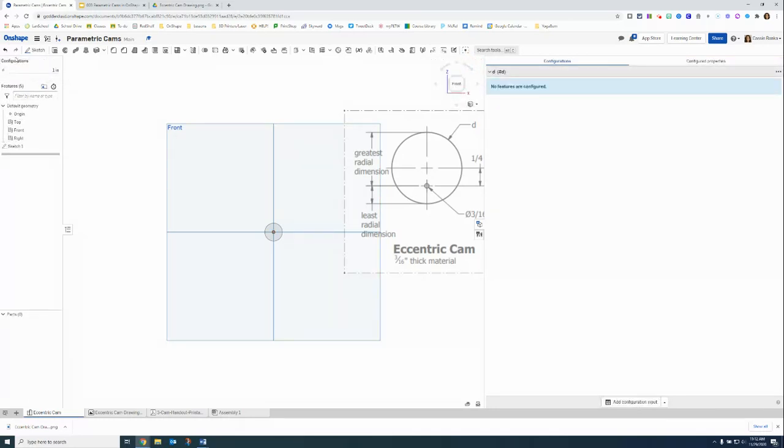Now over here on the left-hand side in that model window, I can see that I've got some variables that are defined. D would be my 1-inch measurement, and this is where I can go to change it if I want to. But I'm going to add a second variable because sometimes this diameter of 3/16 inch is kind of an odd diameter. If I'm looking for dowel rods to be my axle, a lot of times I have a 1/4 inch dowel rod. I might have a 3/16 or maybe even an 1/8. But that 3/16 inch, there's some room for change there.